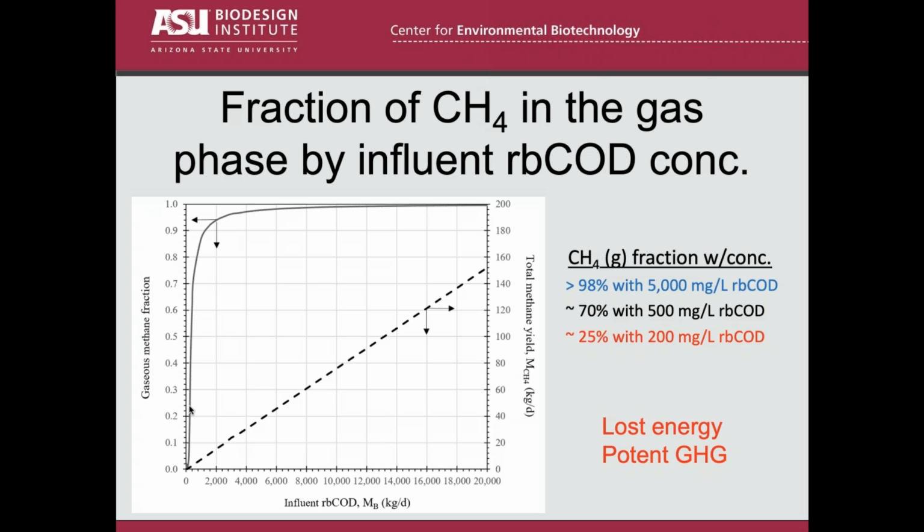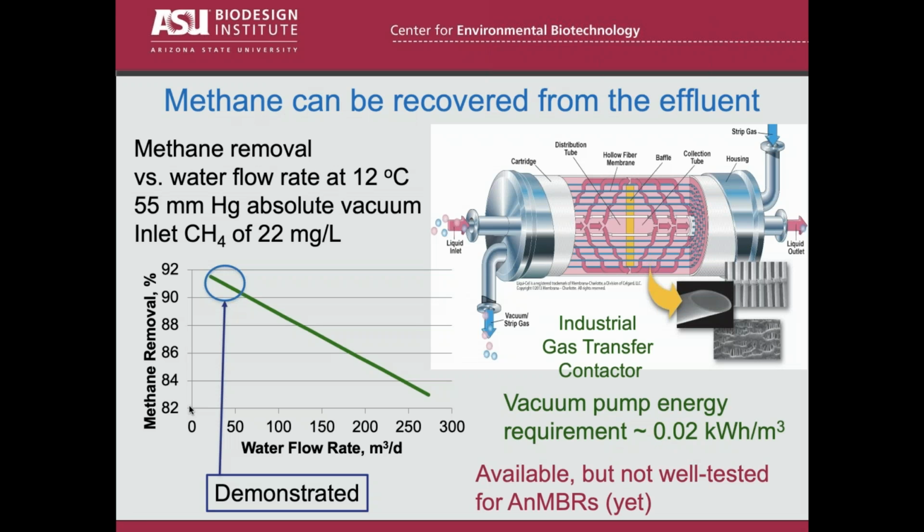All right, now the good news. There are devices available for extracting gases from liquid, and you can do it for methane removal from the effluent. 3M, for example, makes very fine units like this. They have been tested, and you can get 90+% recovery of the methane from the effluent with a very low energy cost. So it's out there, it's available.